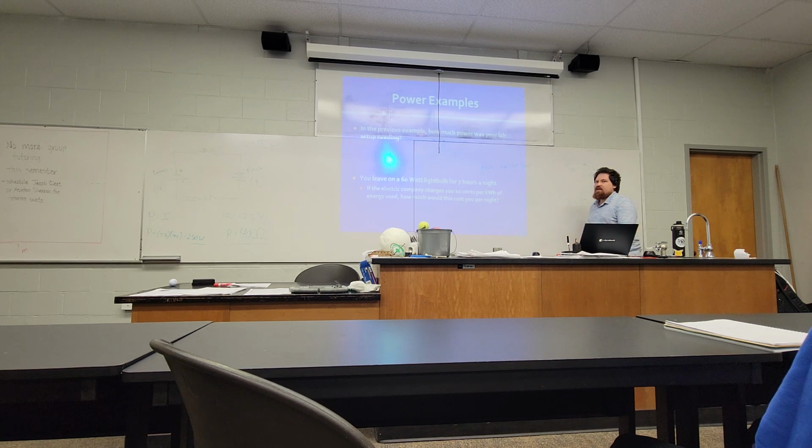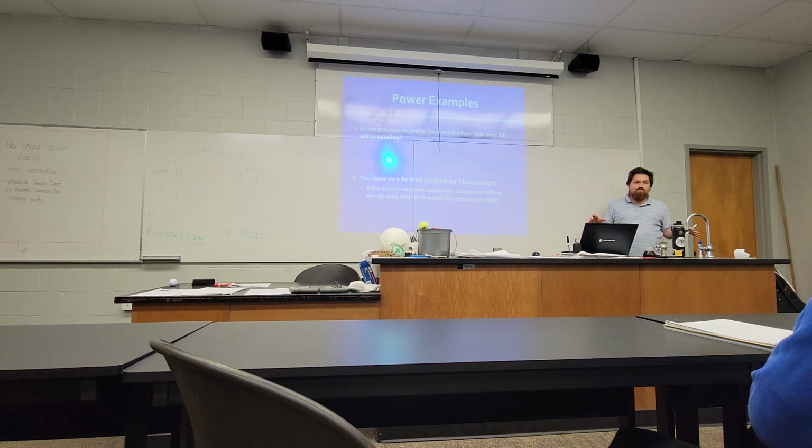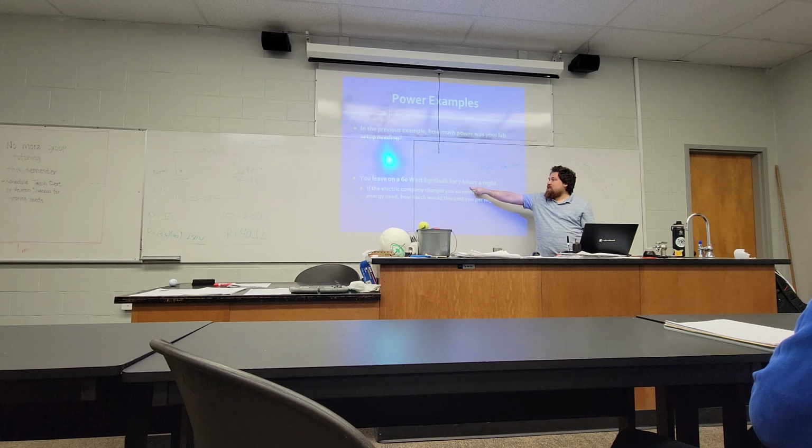And this unit is literally the wattage of your device times the hours it is turned on. It's not kilowatts over hours, it's kilowatts times hours. So that's why it's a hyphen and not the division sign. So the amount of kilowatt hours of energy that something uses is its wattage in kilowatts times the hours that it is turned on. So in the case of this light bulb, 60-watt bulb on for 7 hours,